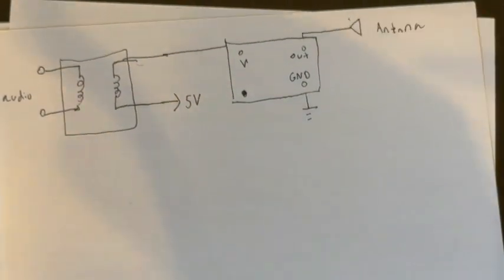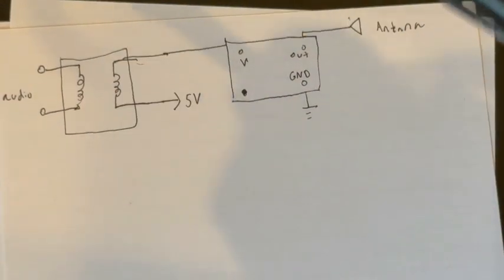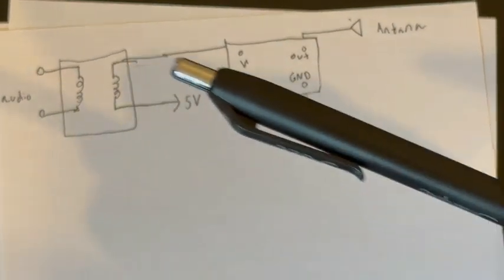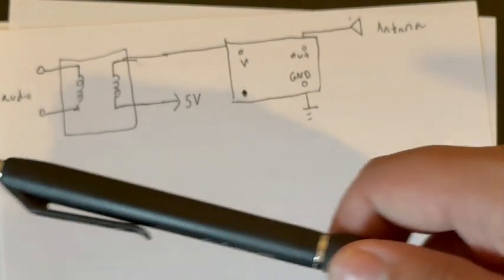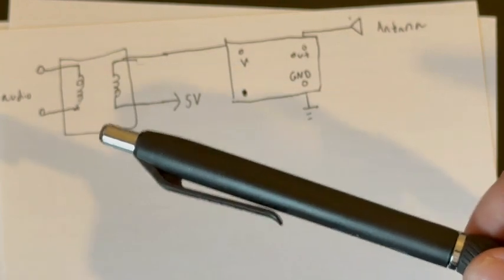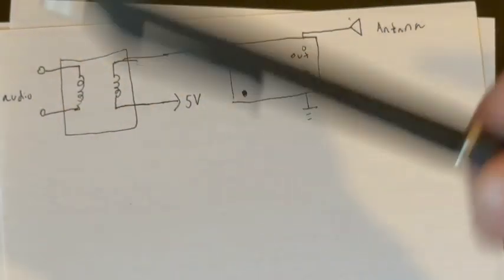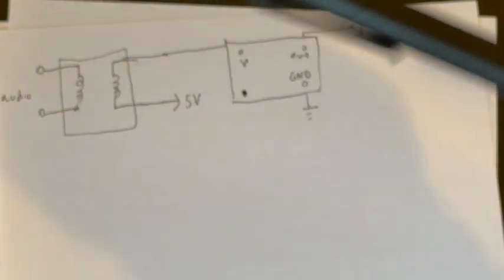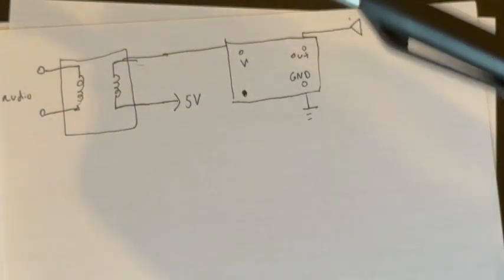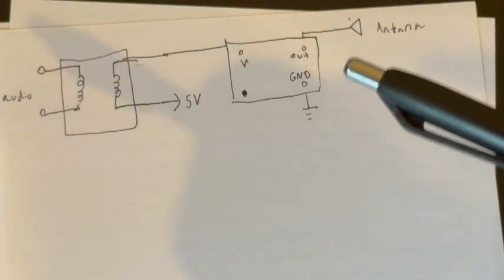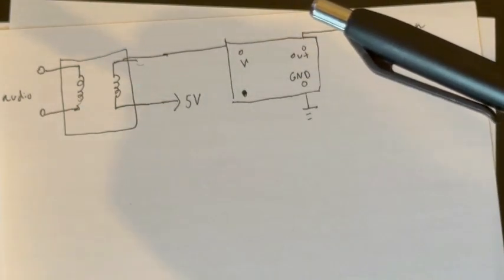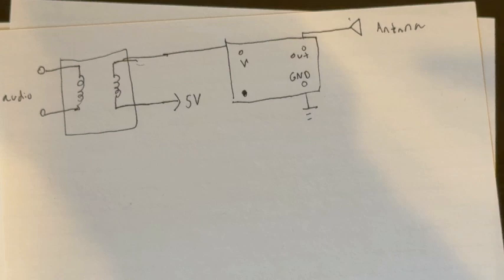Now that we know how amplitude modulation works, we can now build an AM transmitter according to the schematic. To briefly explain, we feed an audio signal into a transformer, which is wired in series with a powered 1 MHz oscillator, and we do this to impose different voltages corresponding to the audio signal into the 1 MHz oscillator, and by doing this we create 1 MHz waves with different amplitudes, and thus we have amplitude modulation.